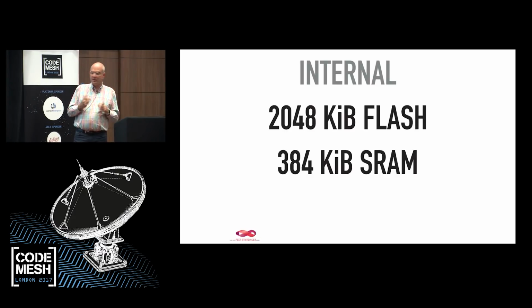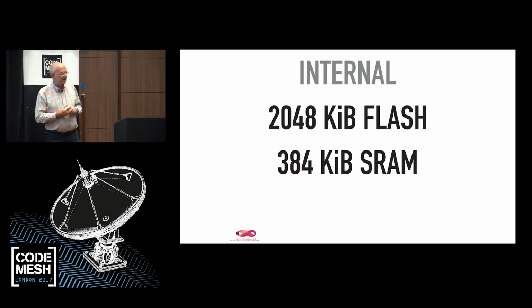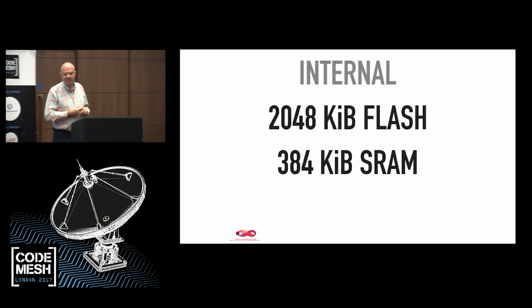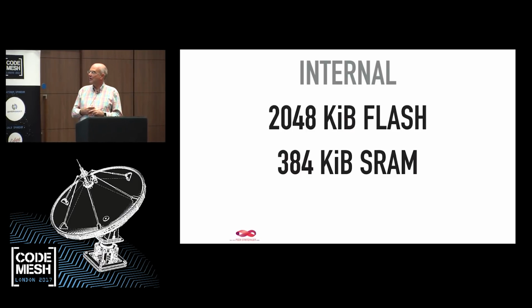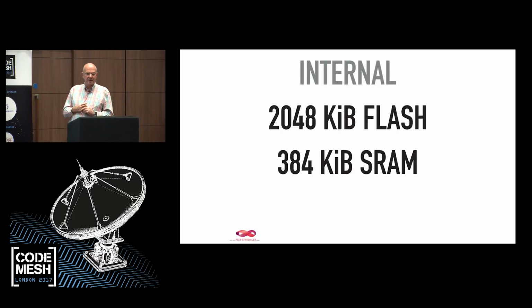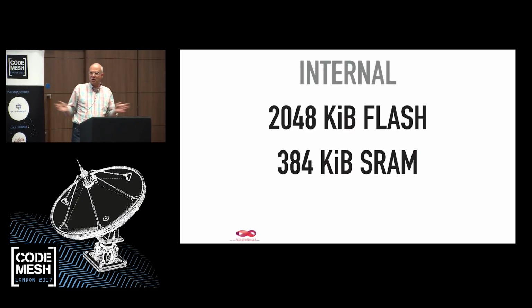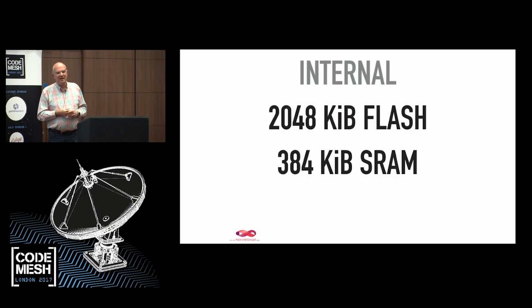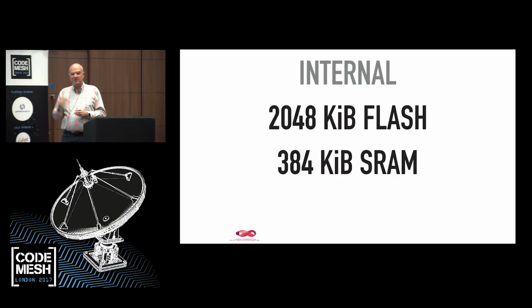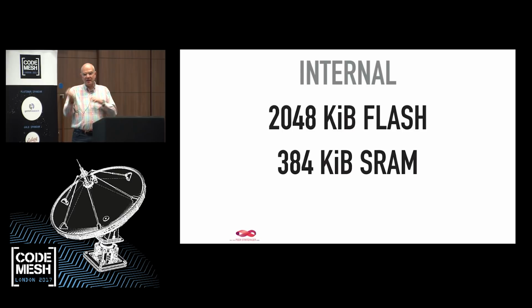into the other memory, into the other RAM, because the 384 kilobyte SRAM is also a little bit little for BEAM. But this SRAM has an advantage. It's unused at the moment. It's free. It's open. So we can do things with it. And of course, it's also very fast because it's inside the CPU, so there are no wait cycles. So we will probably map the inner loop of the Erlang VM into this SRAM on chip and make the whole VM run faster. And for that, it's actually kind of largish already.